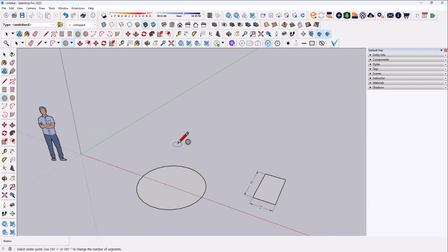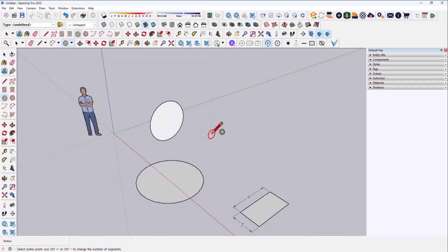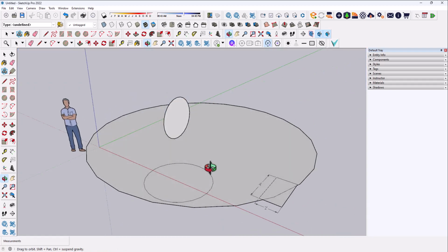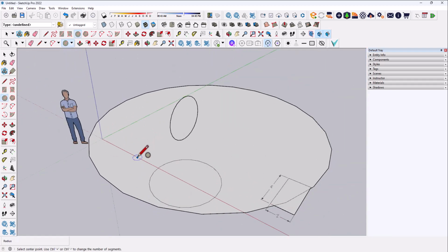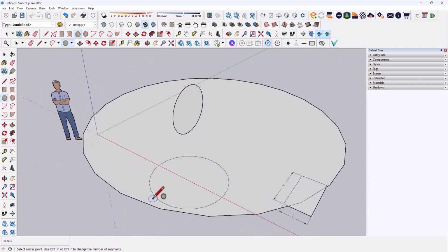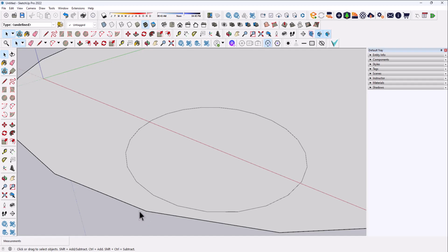Again, if I use the arrow keys on my keyboard, left, right, up, down, I can manipulate the orientation of each of these, so I can choose which plane I want to be drawing in. And you'll notice when SketchUp draws curves, or in this case circles, it's creating polylines.